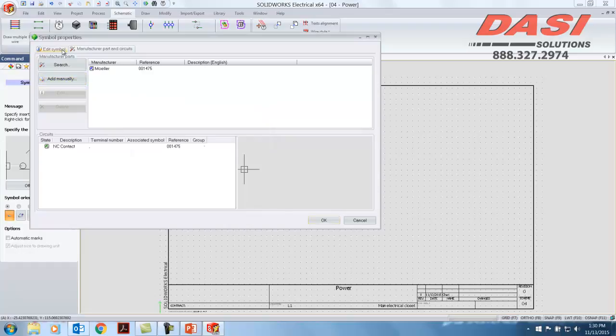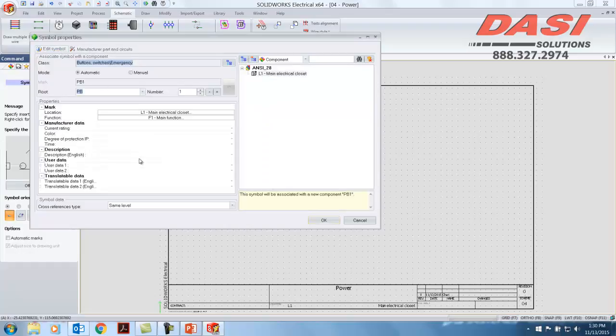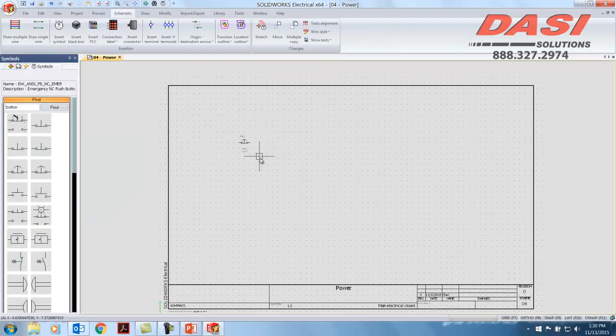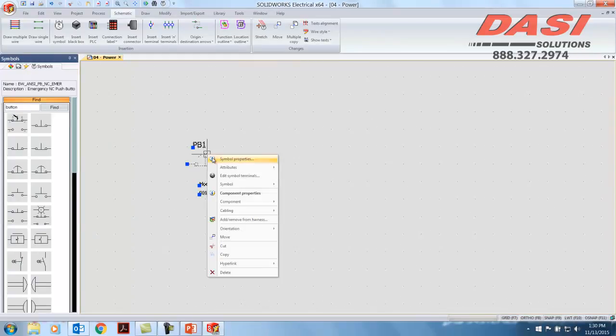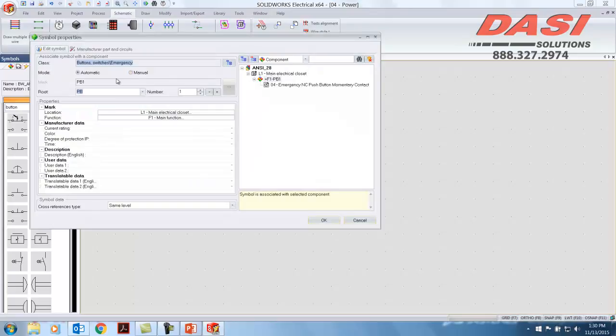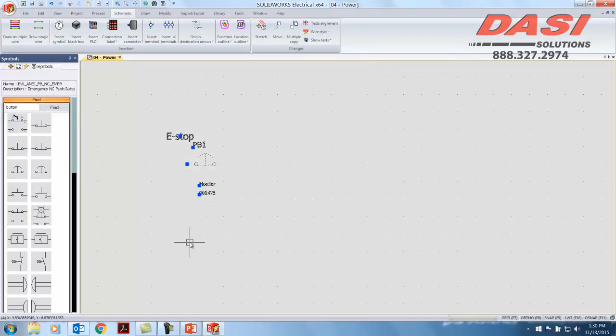All right. Now, this manufacturer right now, the first thing I'm going to do is just go ahead and add it. We'll zoom in here. I'm going to make this have a description that we will be using later for the Lamicoid tag. That's the push button tag, or the ring tag, that you normally put on push buttons on the panel. So I will go ahead here and add a description. We're going to call it e-stop. All right, so here I have this e-stop push button.